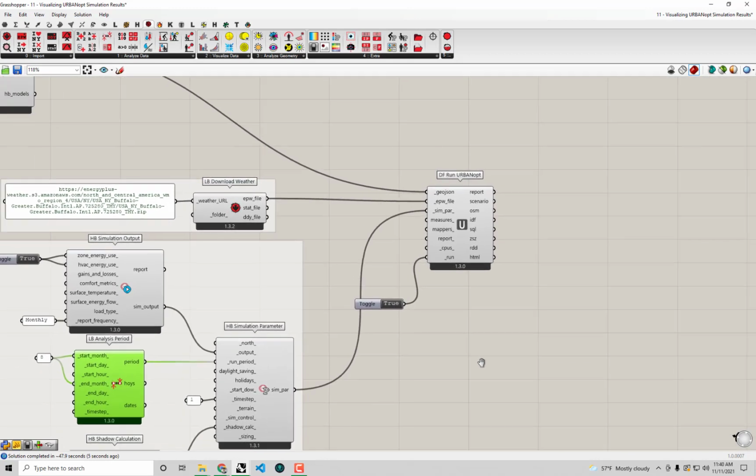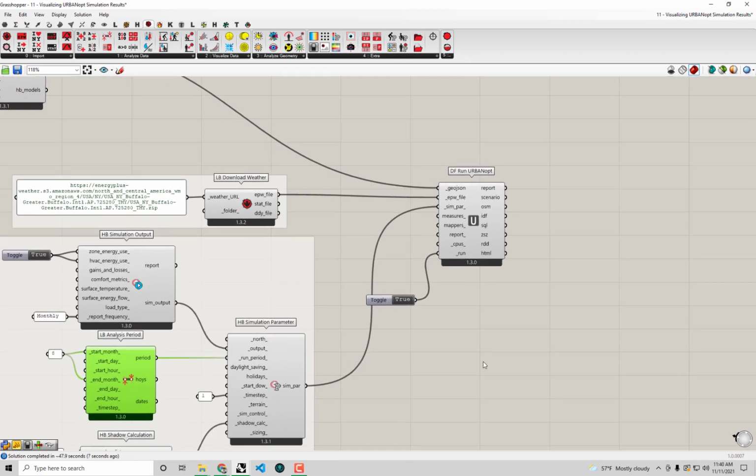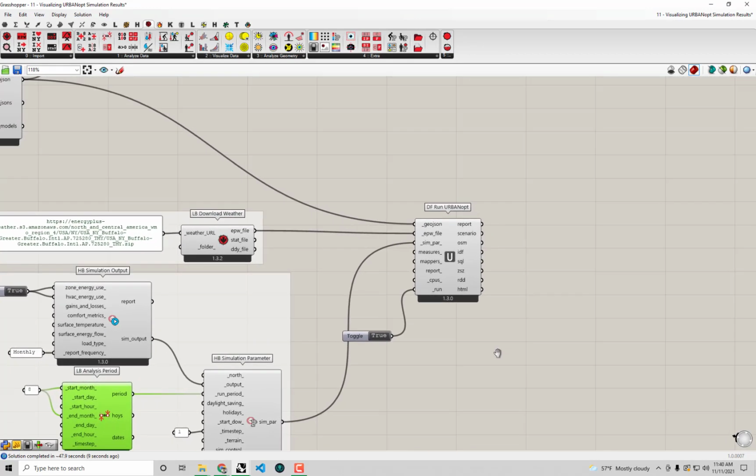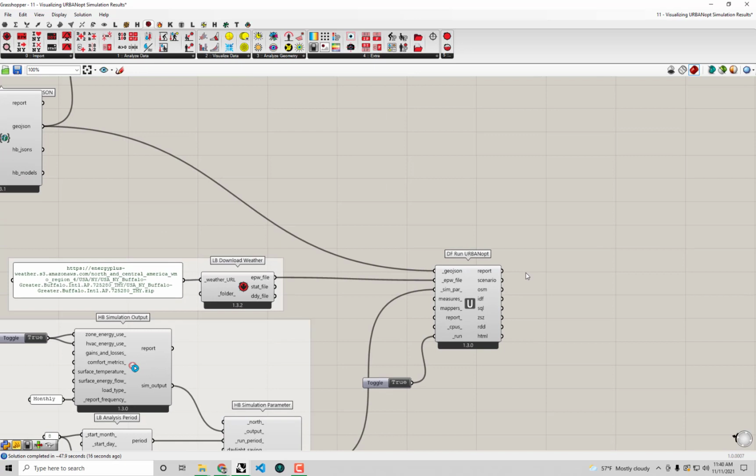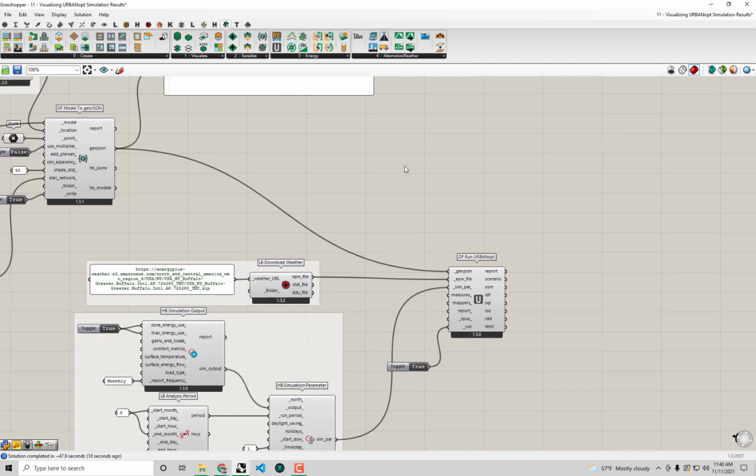Okay, and maybe you guys already sensed that was a very quick simulation because it was only running for a month at a time step of one, a lot faster than what we were running earlier. So great. All right, now we can start to take our electricity usage results that we're getting out of the energy simulation with URBANopt and EnergyPlus and send them off to OpenDSS.